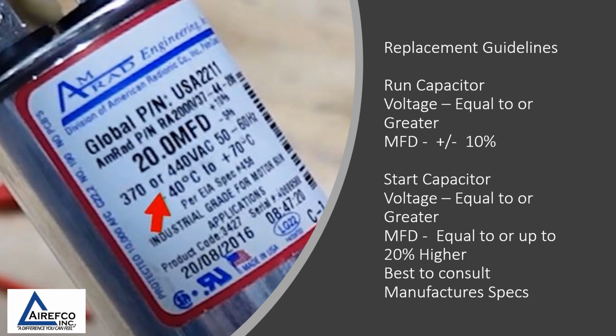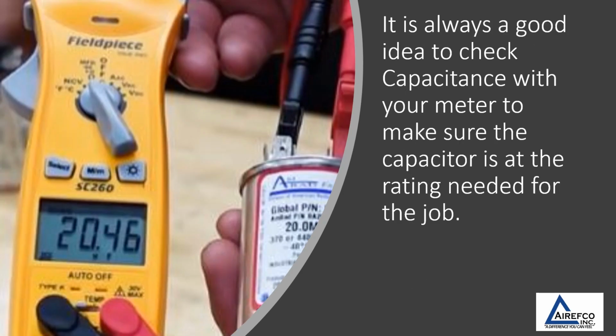For start capacitors, it's best to consult the manufacturer's specifications, as generally these are used on compressors. It is always a good idea to check the capacitance rating with your meter to make sure the capacitor is at the rating needed for the job.